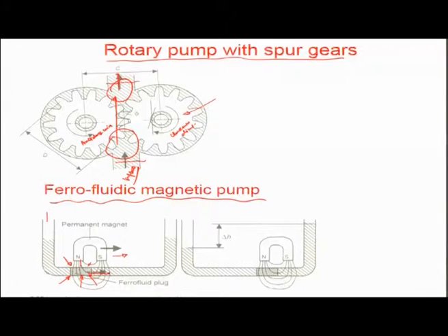And so obviously, if there is a water flow from this end, let us say this is the inflow, the water is actually taken by this plug motion, because the plug will push the water column upwardly on the other side, that is the outlet side, and it will pull in the fluid from the inflow side, so that there is continuity maintained. And so the movement of this ferromagnetic material, like a dispersion, through an external magnetic actuation, would allow for pumping to take place.